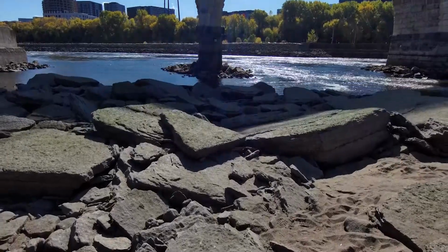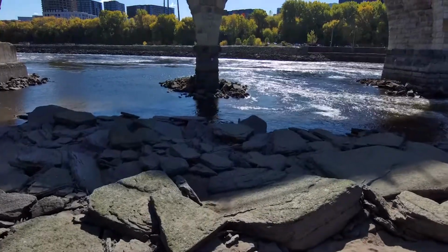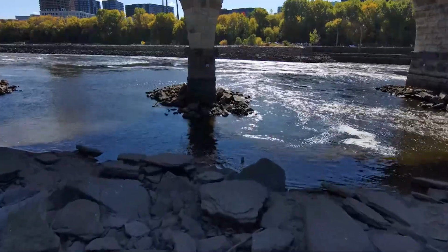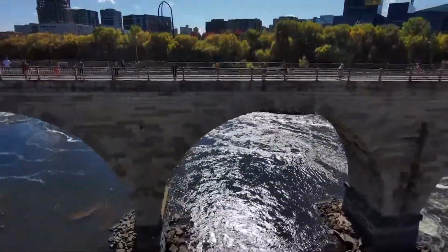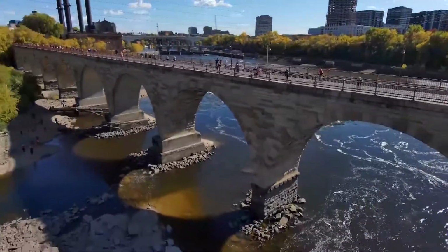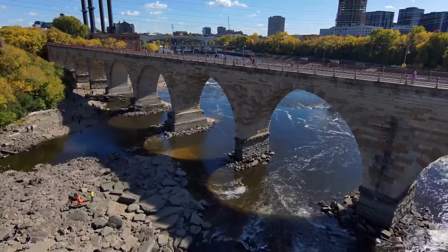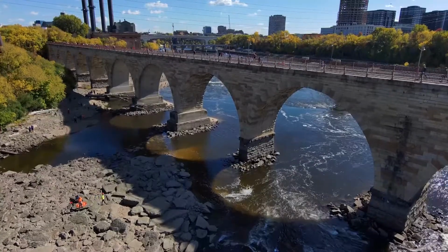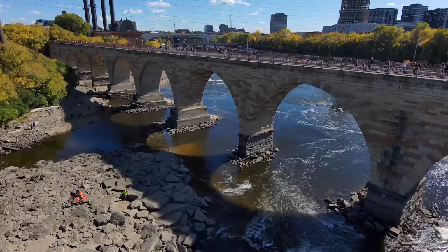One of the unique things about this project is that the Army Corps of Engineers drew down the pool. It's right between 2 lock and dams, and they drew it down for their own purposes, but we took advantage of that, and we went out and reflew these portions of the bridge that were normally underwater, and we normally collect information using just diving. But this was a unique opportunity to collect all that information and have it for design while the water was drawn down, so we could see all the riprap and everything.